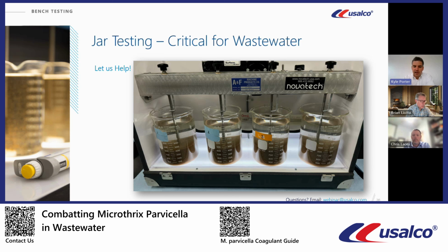This is going to be how you dial in your dose for optimal phosphorus removal. The nice part is that the same dose is generally also going to be that minimum you need anyway, or at least still be above it, in order to prevent the Microthrix from forming in the first place. So you're killing 2 birds with 1 stone once again.